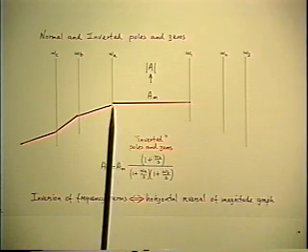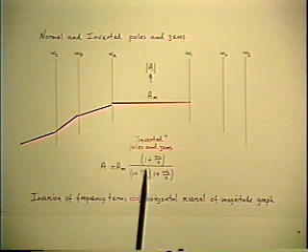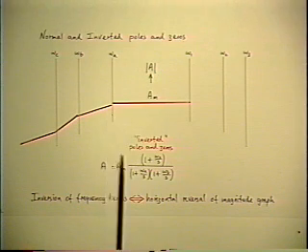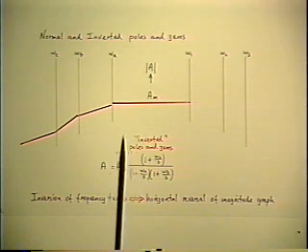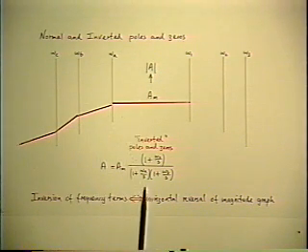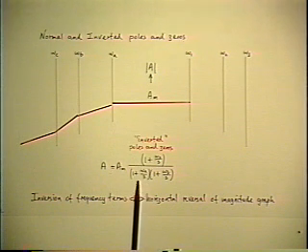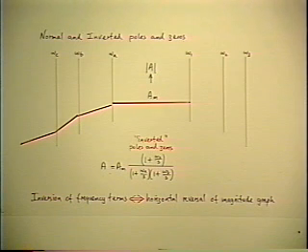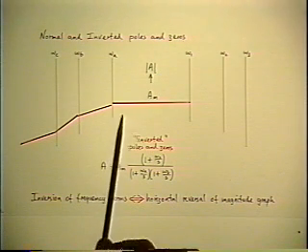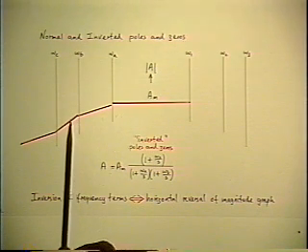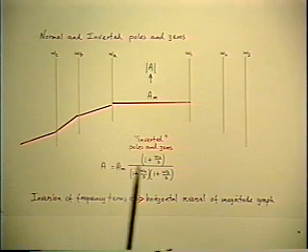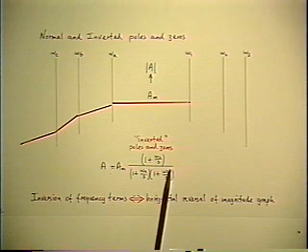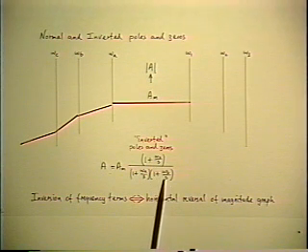As S comes down, when you approach omega A, you have a concave downwards corner, so it's a pole. So the 1 plus term is in the denominator, but because we're going downwards in frequency, it's an inverted pole, so you write it as 1 plus omega A over S. Then you continue down. Same thing happens again at omega B, so there is another inverted pole, a 1 plus omega B over S term in the denominator.